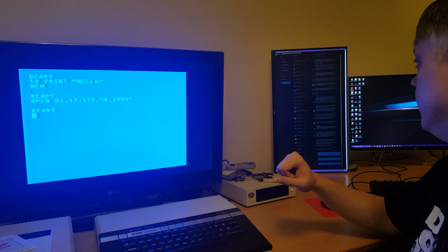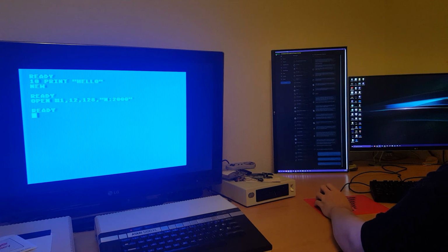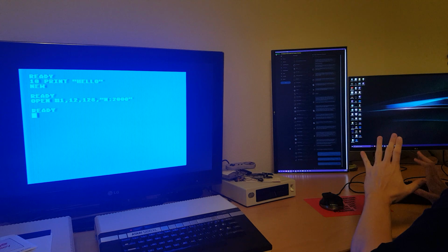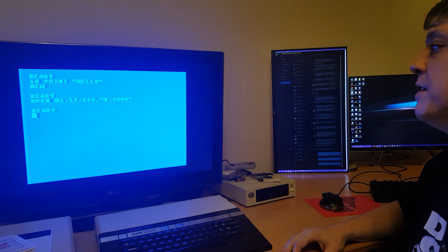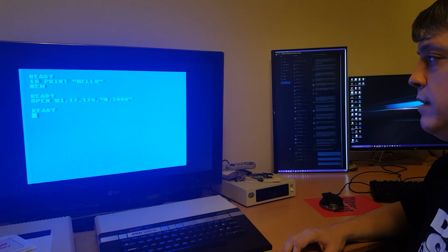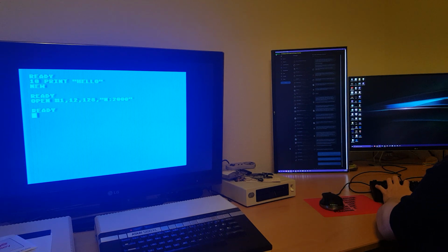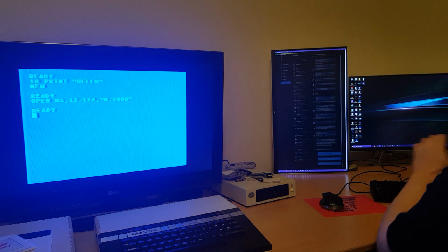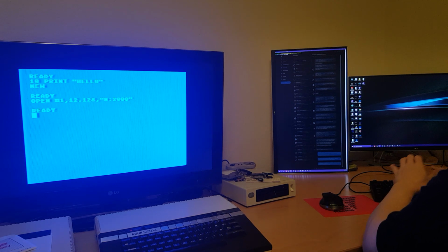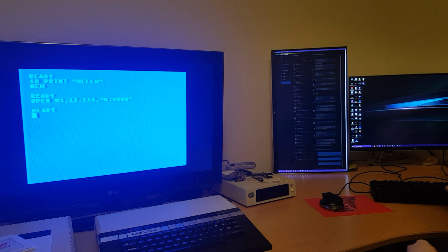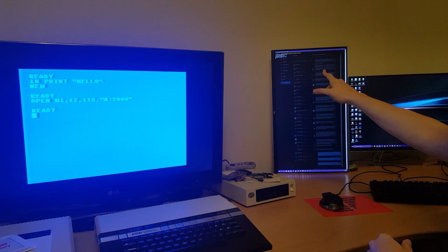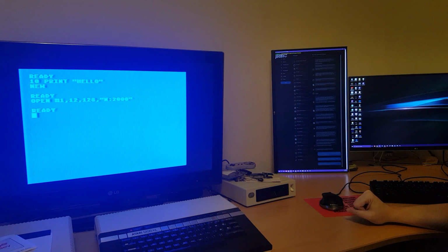So now that this is there, if we were to take a look at the debug output over here, which I don't have up, it would say it's now listening for a connection. So at this point, I can literally do a telnet over to my device here, open up a connection, and you really can't see it too much there, but it says trying, connected, and it's sitting there waiting.